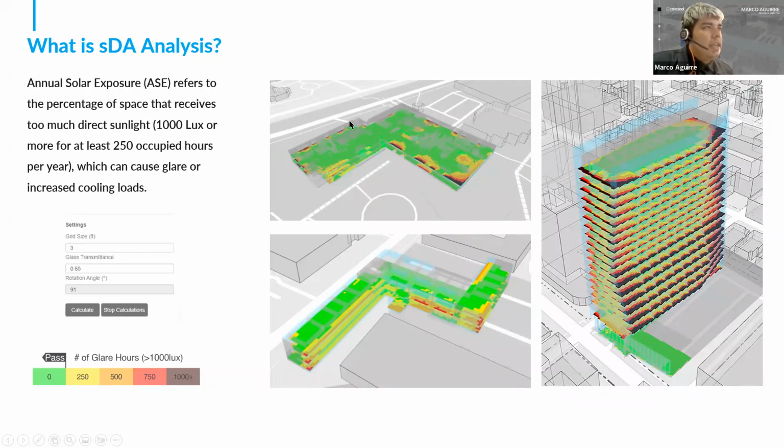You can see that this is a Georgia Tech building that we helped on. Most of the building, since there's smaller openings, there's not a deep daylight penetration, but in the areas where we do have large openings, we do have issues with glare. So we want to think about higher performing glass, things like frits, or overhangs, fins, anything more architectural.